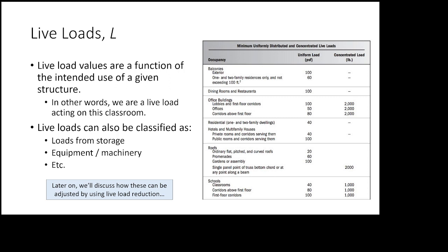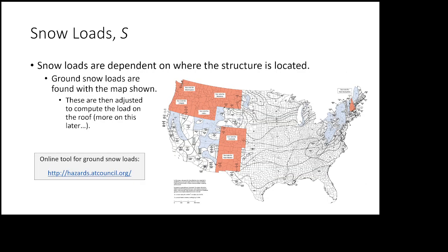But the live loads, I've got much more uncertainty about that. So I'm going to up them 60%, where I might up the dead loads only 20%. Does that make sense? Everybody okay with that? Any questions? All right. Let's talk about snow loads.